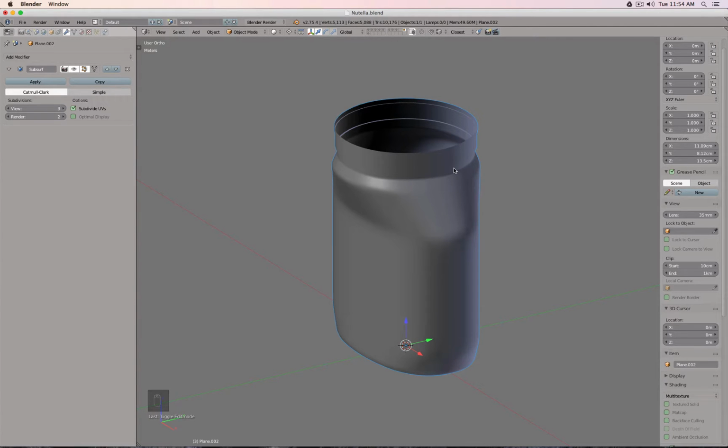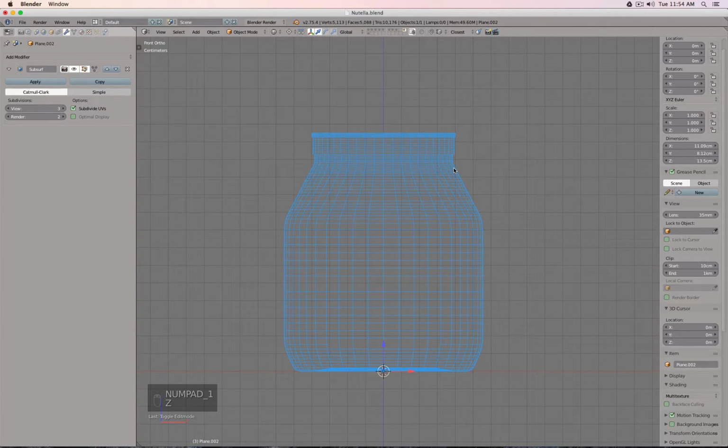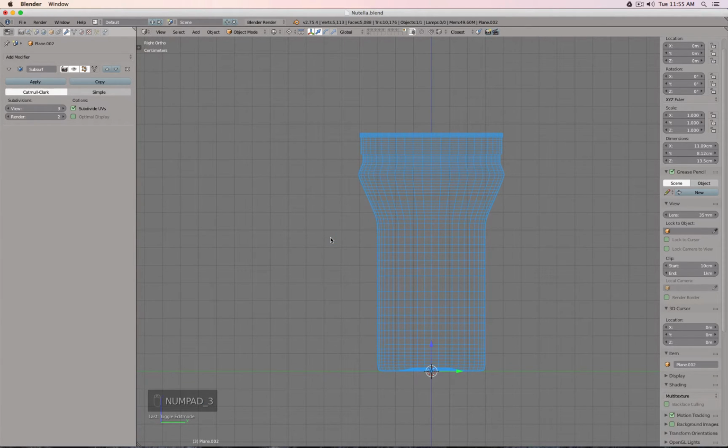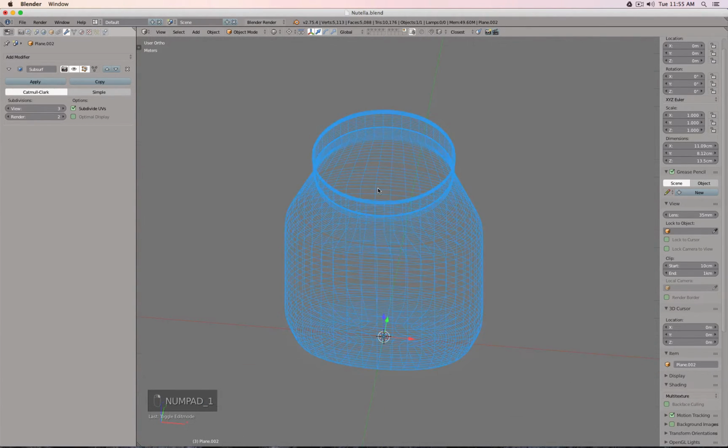But before we do the threading, we have to add a little bit of material thickness to it. Now, the upper ring where we put the cap on is more sturdy, so it has a thicker material, and then down to the bottom it is softer, so you can compress it more. Here you really need stability, here you don't need as much, and wherever you can save plastic during the injection molding process, you also save production costs.